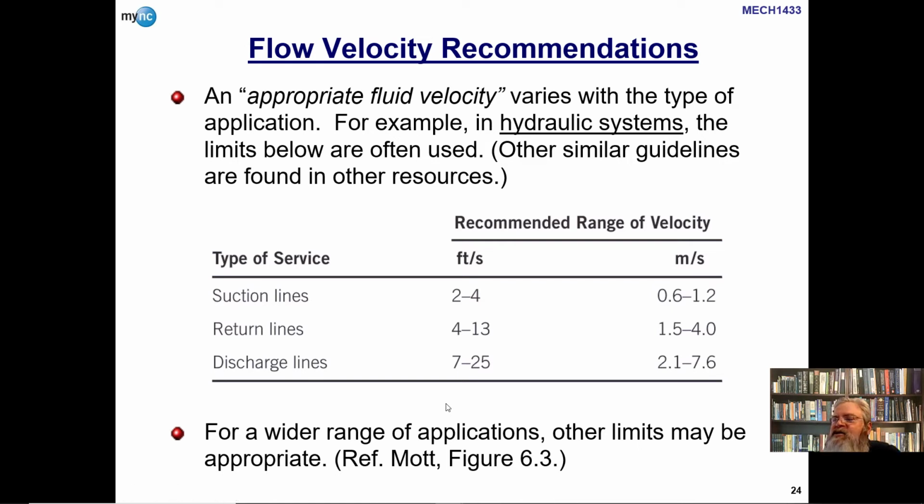It's not like the answer to the question, how big a pipe do you need, has a fixed answer. The answer depends on what you are using as the velocity limit, because it tends to be slightly arbitrary, slightly open to some give and take.